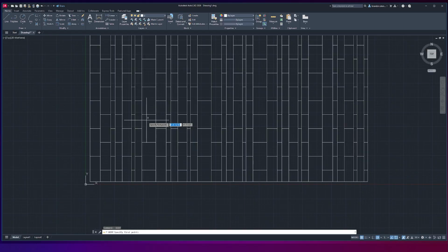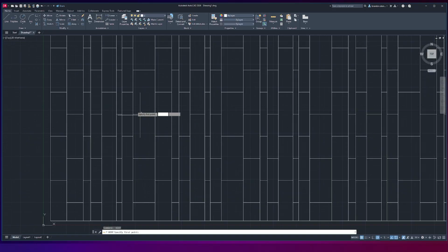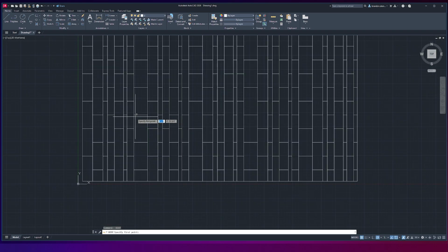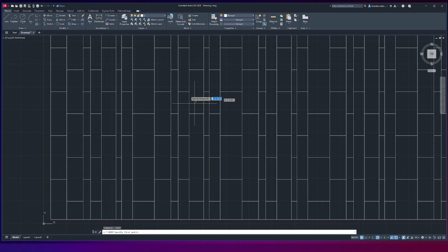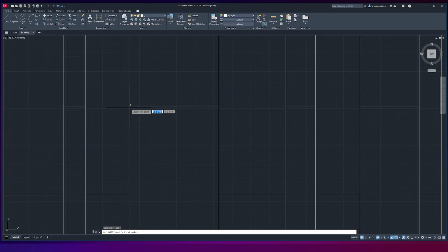That's because AutoCAD doesn't know how we want to tile this thing. I think we could change the offset of the tiling in AutoCAD to align, if we want this shape to be leftmost, we can go into it and drag it over. I'm not going to get into how to do that. You should be able to find a tutorial on how to move a hatch inside of AutoCAD. But essentially what we're going to do is we're going to try this again.